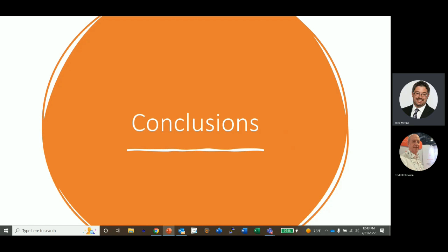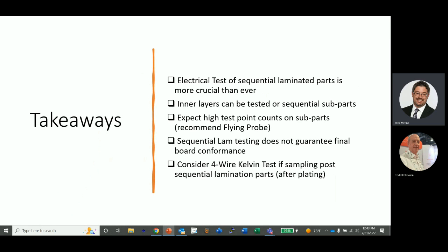As we were talking about earlier, Todd, most of the AOIs and AVIs in the market right now are single-sided, but there's a small percentage now that's growing and growing as people start to automate their plants. There are dual-side AOIs, dual-side AVIs, and some of them even come inline. So coming off of your plating line or etching line, you can have AOI right there doing inspection on your layers or inspection on your final.